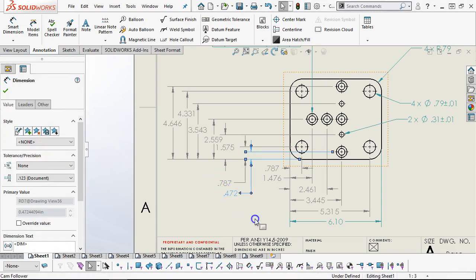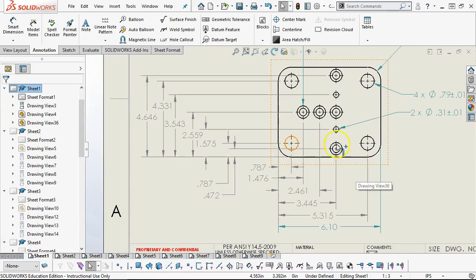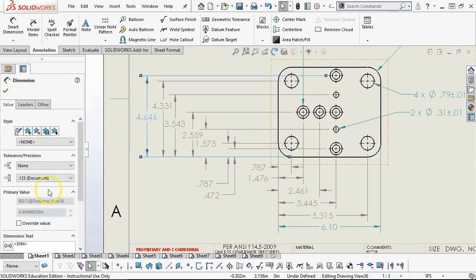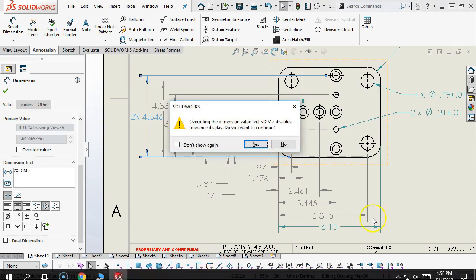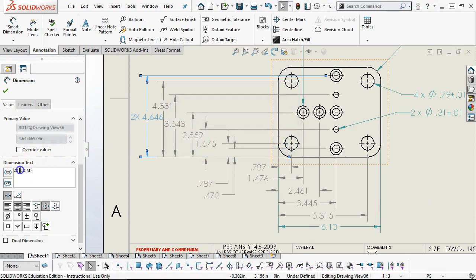All right. And then as far as the extension lines, we have 2 items, then 5 items. All right, so if I were to drag the extension lines through, that would be the notation that it is for both. But since I didn't, we're going to go to a 2 times notation, which is going to stretch it out a little bit. And I deleted the bracket, so it warned me. All right, so I have a 2 times.